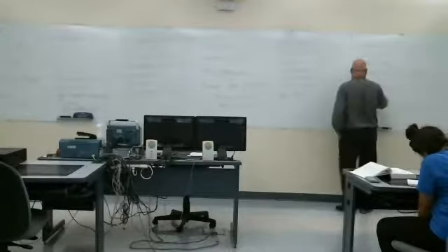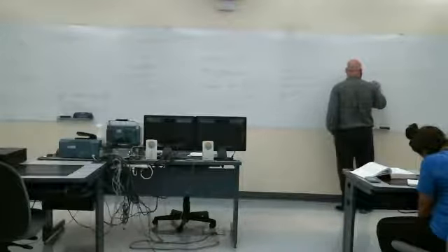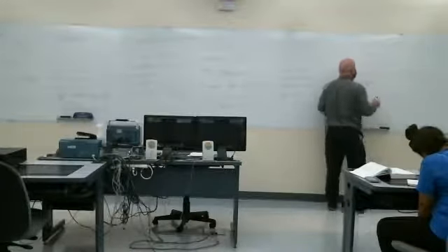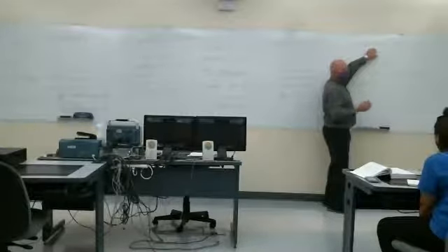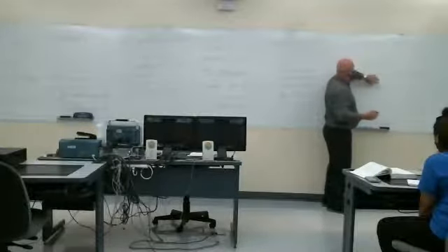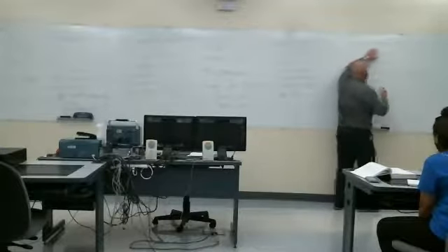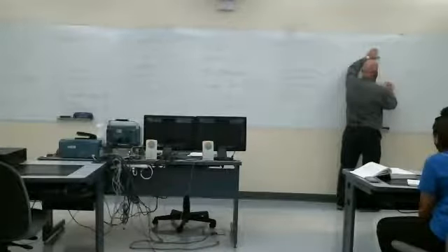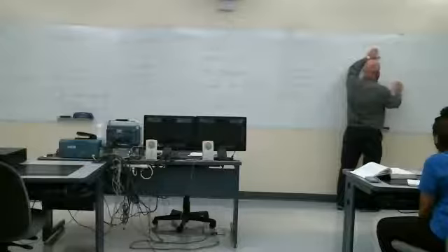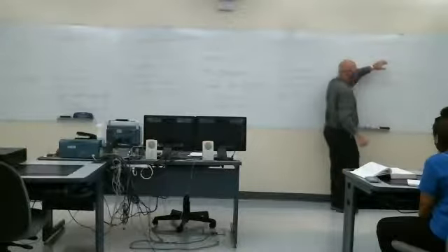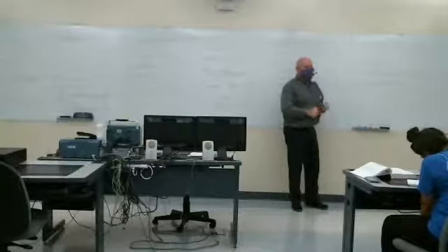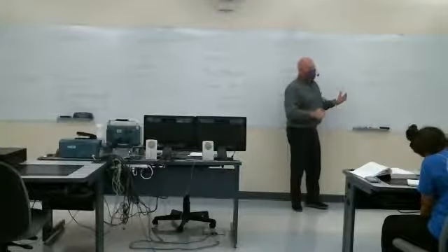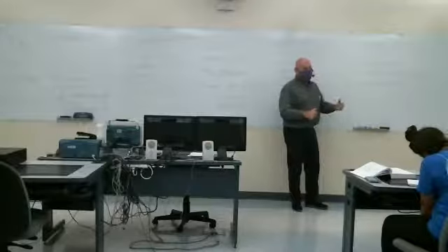Now, what is y of t minus delta? Well, this is y of t. So what would that look like delayed by delta? I substitute t minus delta in everywhere for t. I get 3x squared t minus delta. And they're equal. So this would be a time invariant system, but it's not linear.